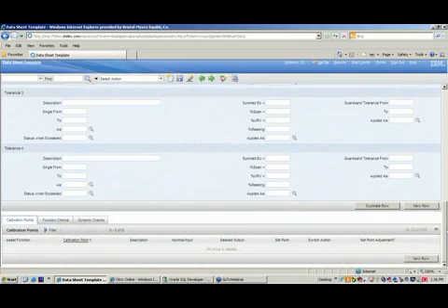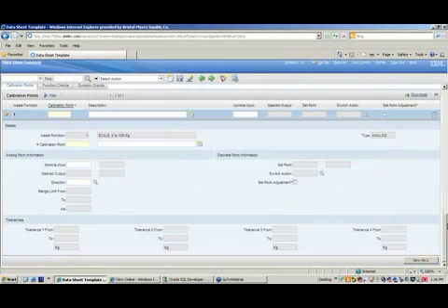The next stage to do is actually add our calibration points to this data sheet itself. Again, we invoke a new row. You may add as many calibration points to each asset function as necessary. Calibration point, again, is a numeric value, so we define it. And this one here, we're starting at, say, 0 kilogram as our first measure point. So our nominal input would then be 0. In doing so, we see automatically that the tolerance range, because we defined it in units, is automatically populated, allowing the system, or you, the user, to see what the tolerance range is.